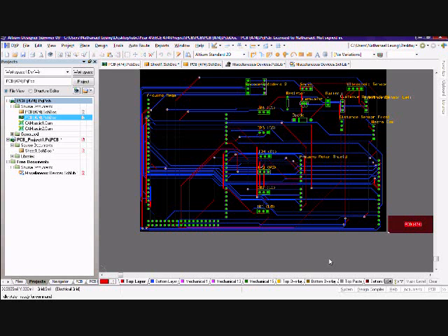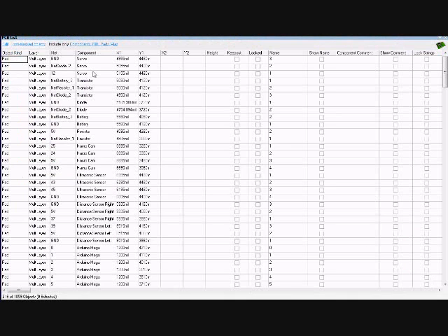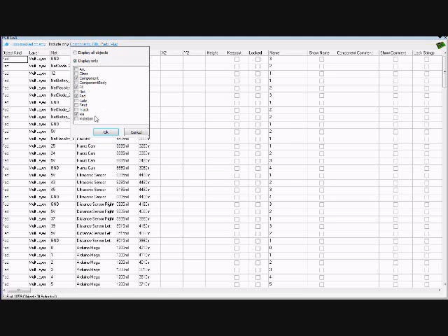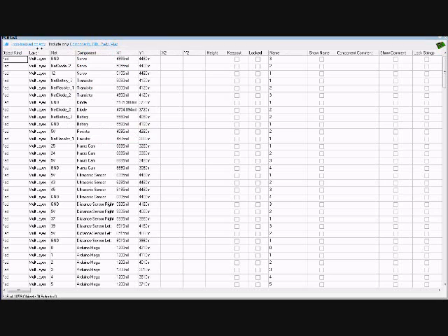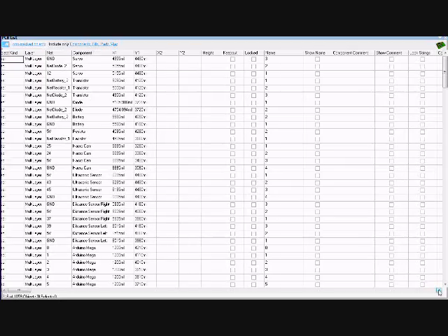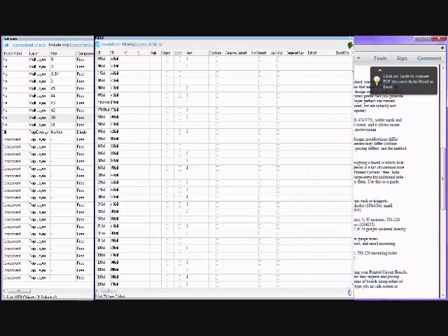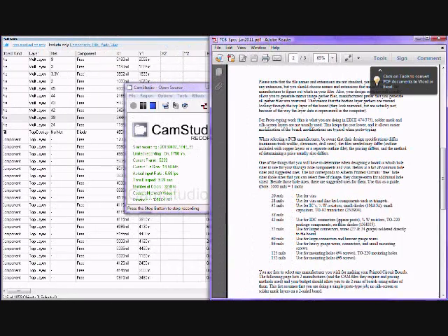After you have completed creating the PCB, your next step is to inspect the PCB to make sure that all specifications are correct. So you click on PCB at the bottom, click on PCB list, and this will show up. What you want is to include components with the vias, the pads, and the component fields. Next, you click on edit here so that you will be able to edit the components, double checking. And afterwards, you will scroll over to the right side, to the hole size. As you can see, the hole sizes of the components are located in the specification document that was provided by the course website.